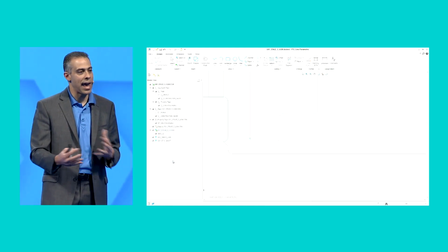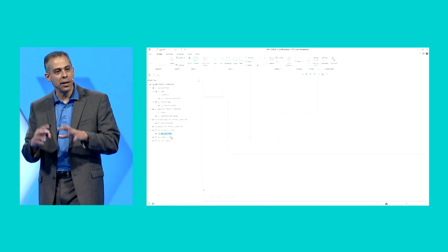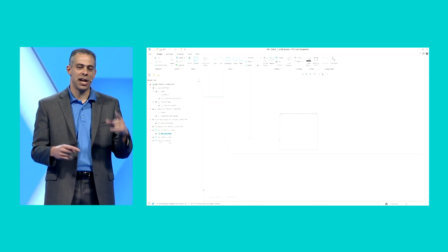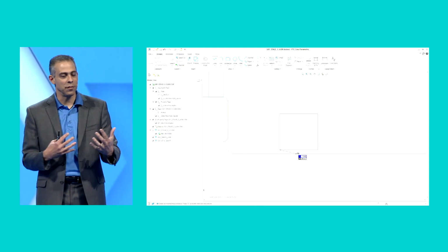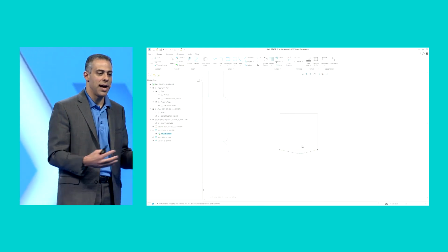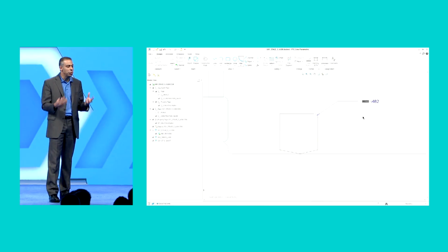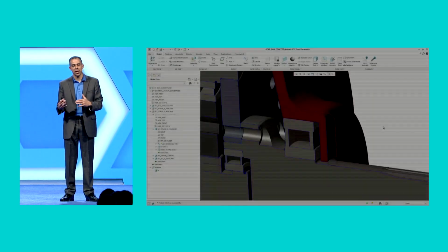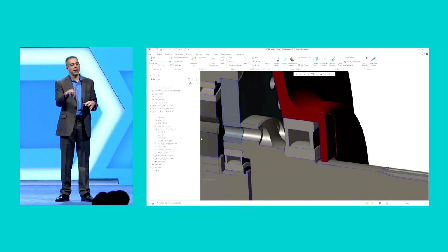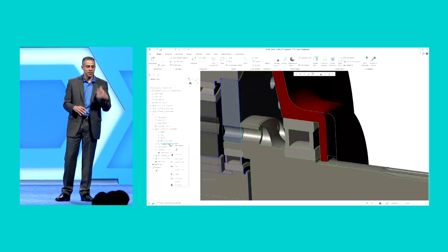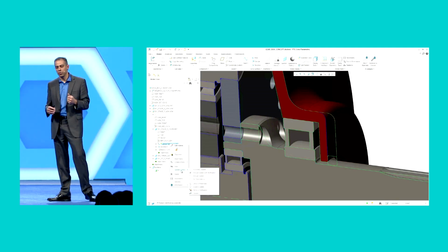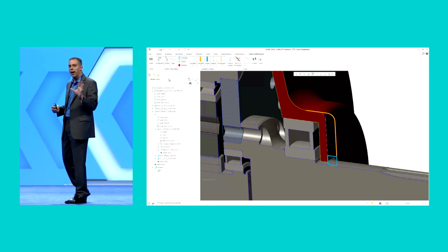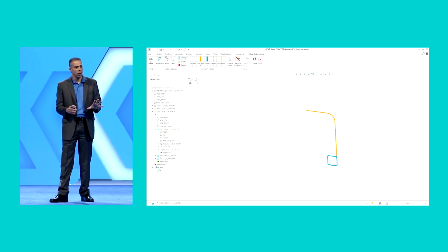So there's quite a bit of work happening here in 2D, but in Creo 2.0, all of that work will be represented in a single change of a single feature. So you have to kind of accept that, and hopefully you can visualize what the changes are. In Creo 3.0, we're going to give you entity by entity updates on exactly what's changed in the 2D environment. So here you see I've got some outdated geometry, and I have this ability in Creo 3.0 to show the differences. I can actually see the differences before I accept the changes in Creo 3.0.